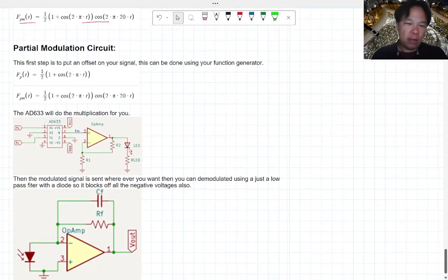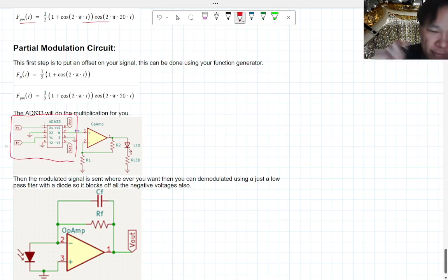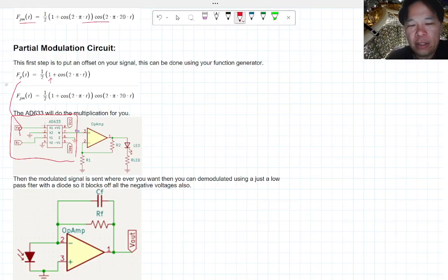Okay, so how does the amplitude modulation circuit work? The modulating side, the left-hand side here, is basically the same. The connection is the same, but your Fs, I'm just copying that over, sorry about that, has to be shifted up. It has to have this offset. So if the amplitude of your wave is 1 volt, you have to shift it up by maybe 1.1. You want to stay away from 0, right? If the amplitude is 2, you need 2.1, and so on like that.